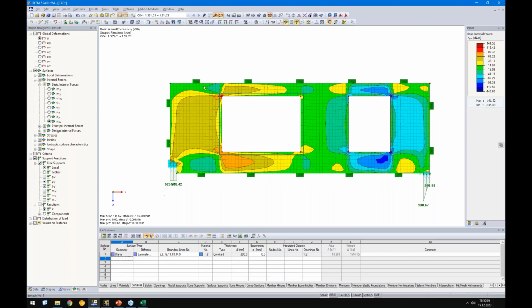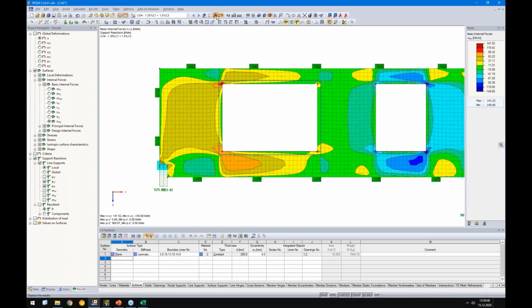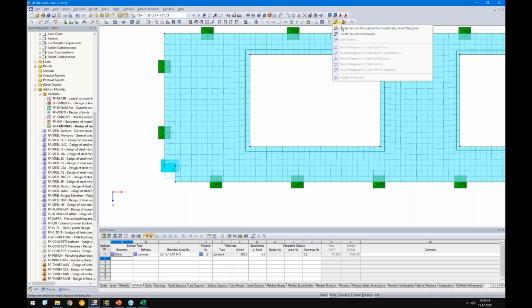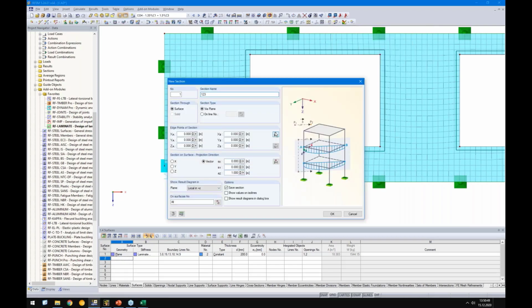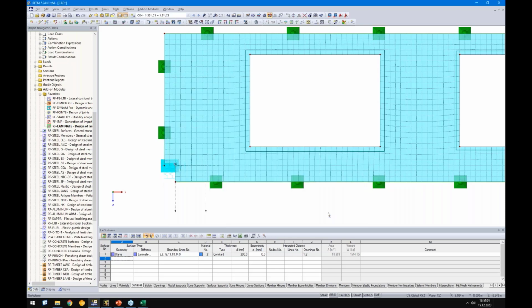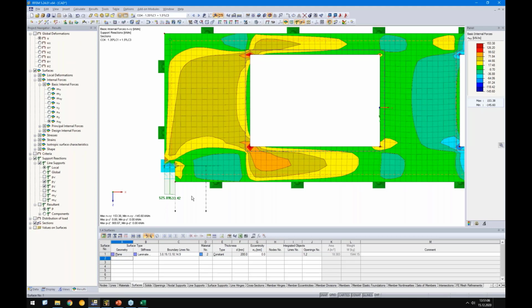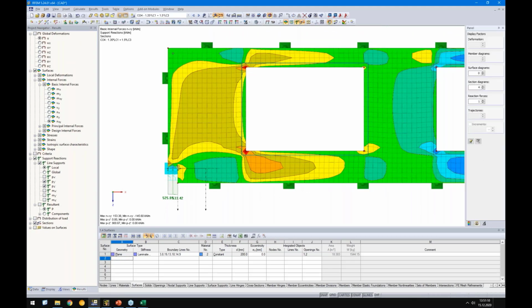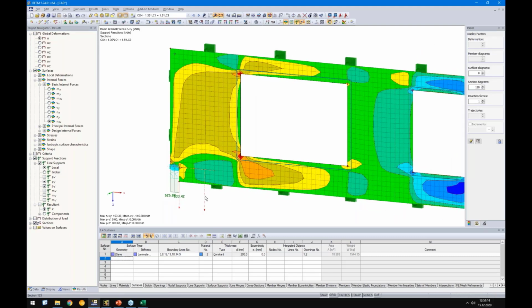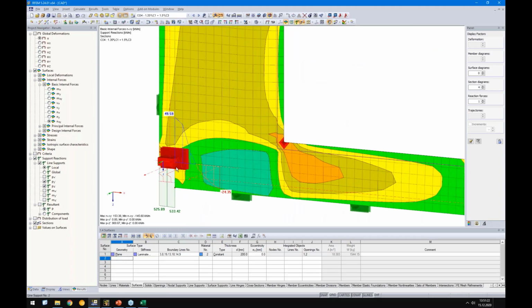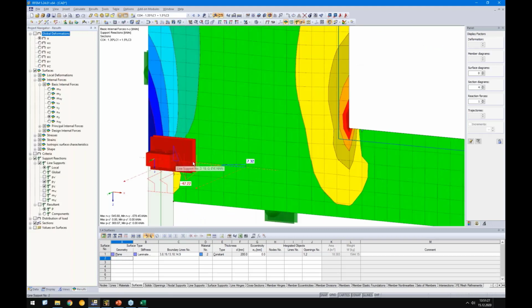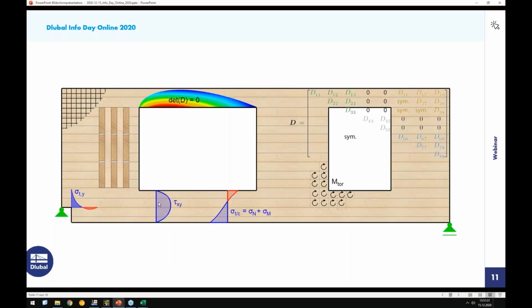Okay, so then let's check this notch result here, and in this example I will create a simple section. The section should start here and should go to 5.5 meters for surface number 1 in, let's say, -c direction. Now, wait a minute. Of course, the section must go out of the plane, and then you see exactly here this stress. In this case, I used NY. Maybe better to use a finer FE mesh here, and then you get this typical transversal tension curve, which is shown here.